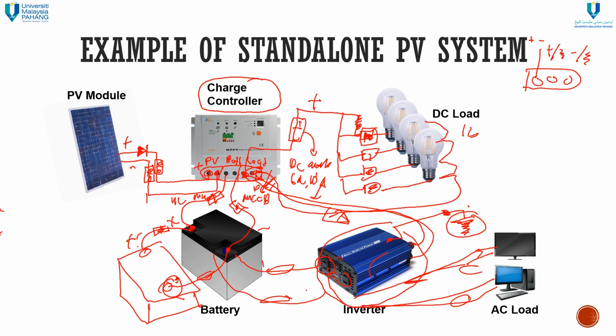If you connect directly, you can get a continuous power supply, but the problem is it will not trigger if the battery is getting very low. Even though they have a limitation here for the inverter, basically we will overlook it, because they don't have any indicator or safety features that stop it. Mostly they are not equipped with that. But the hybrid inverter for the standalone system is equipped with a good controller. That one is different.